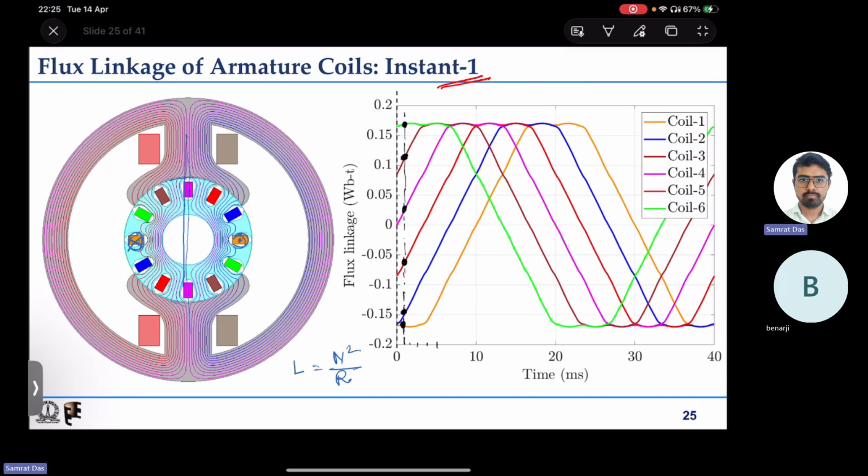That is correct. Now if we position the brush for this rotor position, and if we see the equivalent circuit, the current path basically, then we will see that two of these same induced EMFs will come in series, something like this, and another coil will also come in that path, but that is shorted, with zero induced EMF.